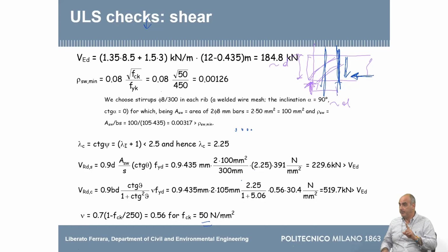This is important, because even if the failure of the shear is governed by the steel, so by the ductile part, shear is always a brittle mechanism. Bending is a ductile failure mechanism. So if the safety factor of the bending failure mechanism is lower than the safety factor of the brittle failure mechanism, it means that wherever it will happen, the ductile mechanism will occur first.